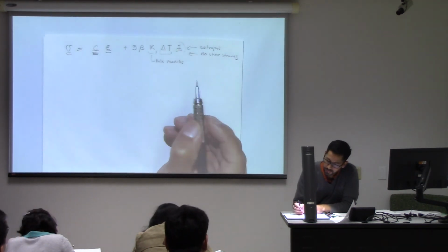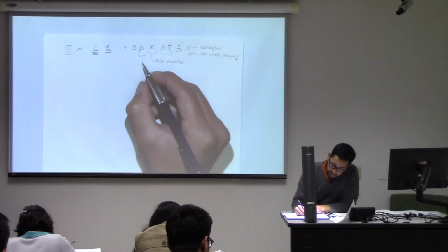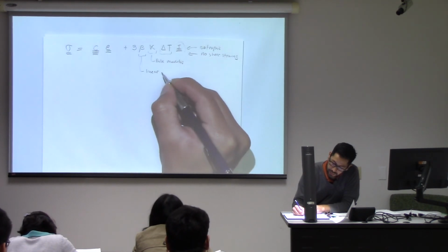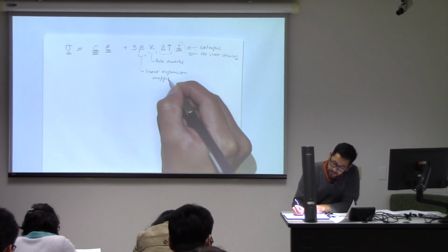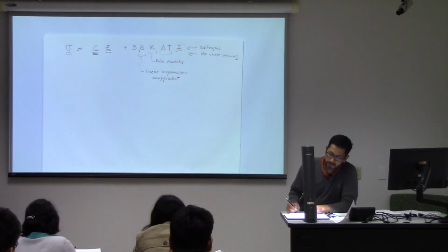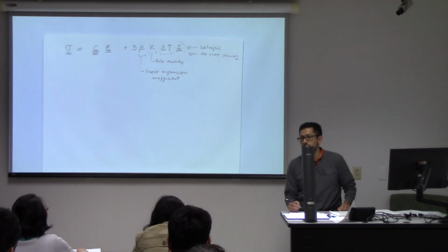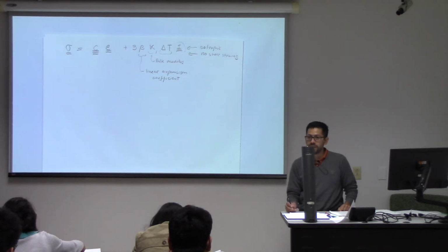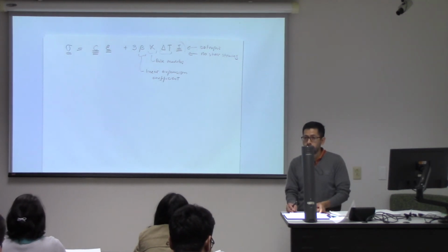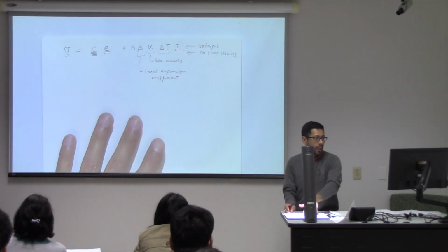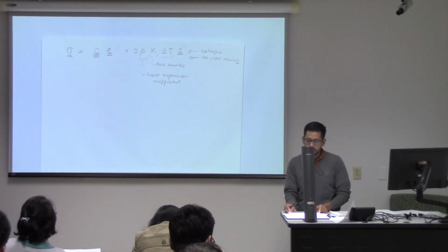And here, this is going to be the linear expansion coefficient. Is it the same as the thermodynamic one, at constant pressure? The linear expansion coefficient? Yes, this is thermodynamic beta, so 1 over V. Yeah, it's the same thing. But now we're putting it into the context of linear elasticity in 3 dimensions.